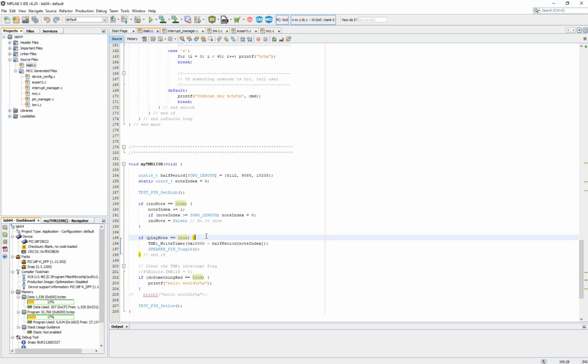So when you press it, in your main code you give it a true. Whenever it interrupts, because you cannot control the interrupt, like I said, if you turn it on, it's going to interrupt every 4.1 milliseconds. It's going to get into it no matter what you have done in the main C code or what the user has done with the board. So whenever the user does something with the board, you want to use a flag to control it.